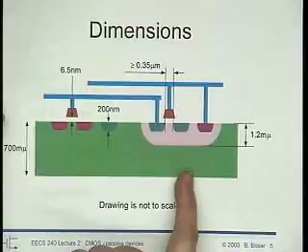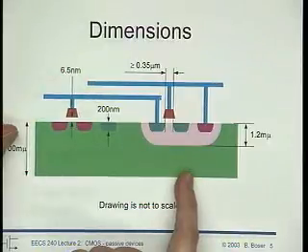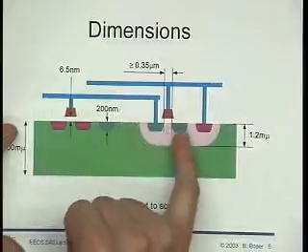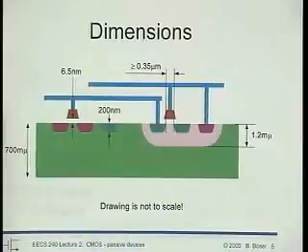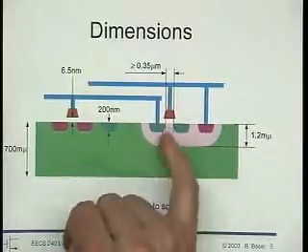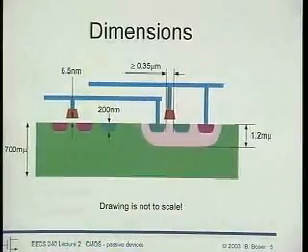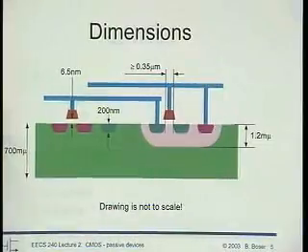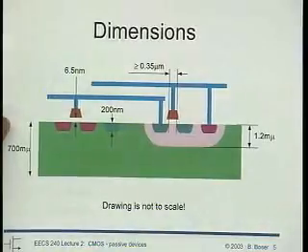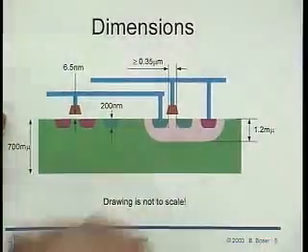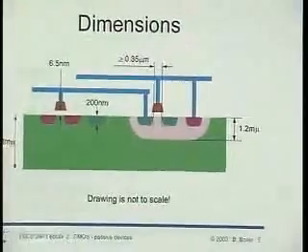What do you think? Heck, what's bigger? The substrate is all around it, and then there is this small junction somewhere over there, right? So if you forward bias this diode, most of the current actually ends up in the substrate, like 90% or so. So these diodes are conditionally useful, right? If we want a diode to the substrate, sure, we can have it.